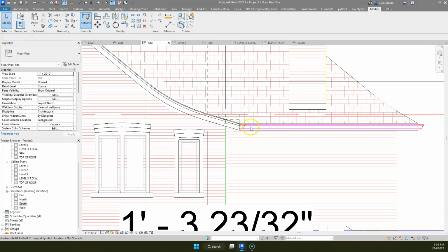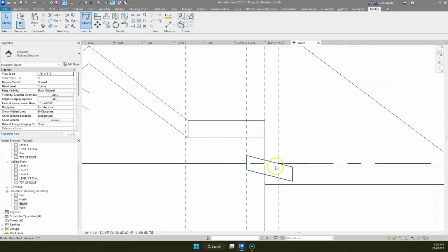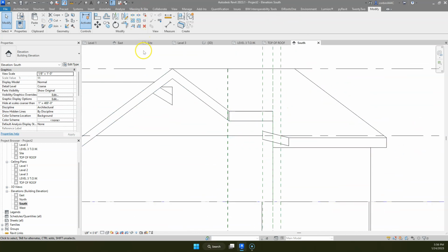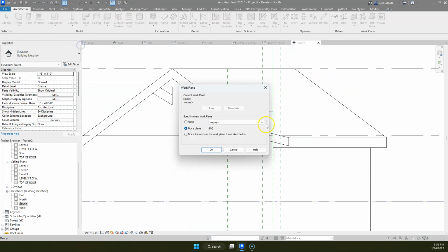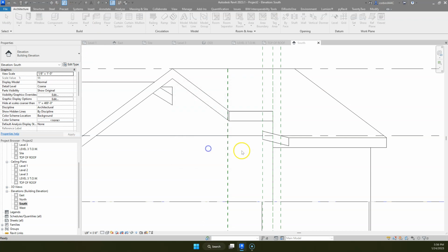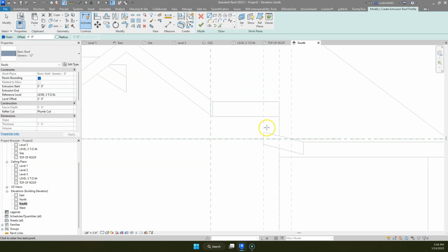Yeah, okay, it's the same eave right there, right? So we can align the eaves. And now the tougher part is to do that curve. To do this curve, I don't really like doing roofs by extrusion, but to do this curve, we'd want to do roof by extrusion. Pick that wall, top of wall here, and essentially what we're going to do is just add a curvature in there like that.